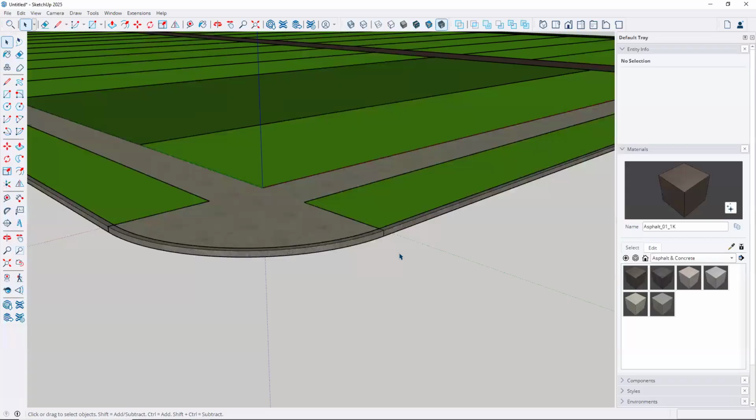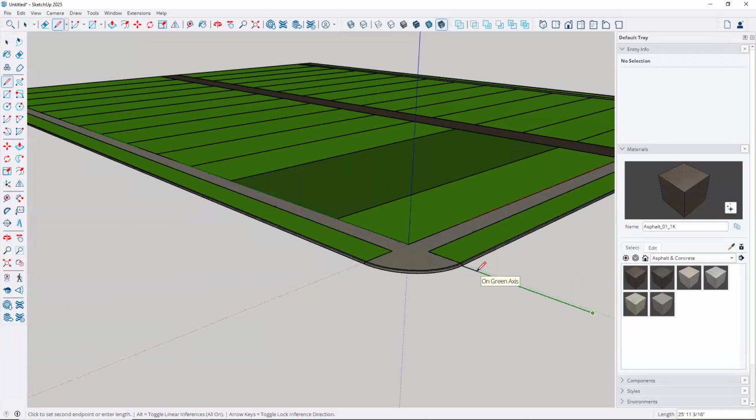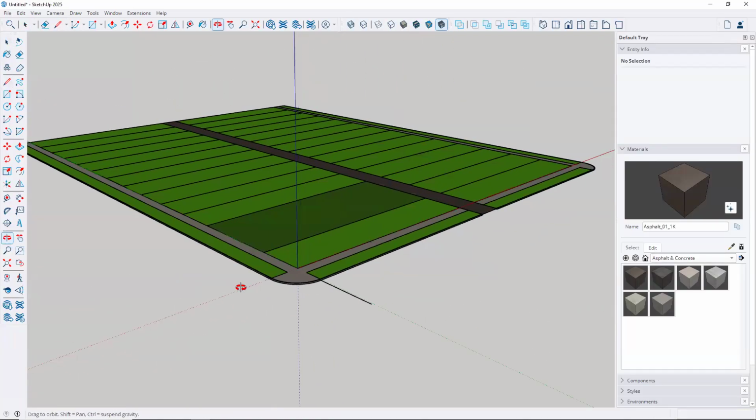And I know I want my street to be at least 30 feet wide. And I know I want my street to kind of drop below my curb and my sidewalk here. It's got to start down at the bottom. So I'm going to type L. I'm going to start right here. I'm going to take it out 30 feet. Enter. That's a line, and then I'll tap the escape key and the space bar. So that's 6 inches lower.